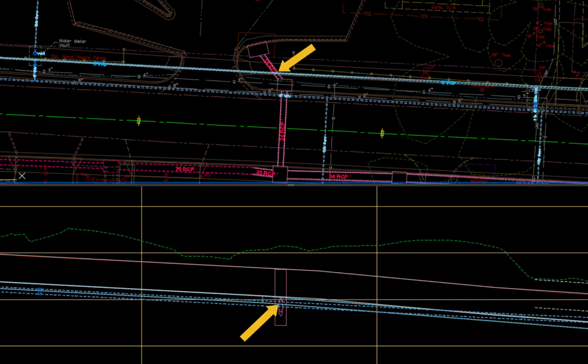There is a conflict with the storm pipe crossing around station 15+60 in Kincaid. The water pipe could be deflected below the storm pipe. The storm pipe could be lowered, which would possibly require the lowering of the sewer pipe. The normal 30-inch minimum depth of cover for a water line is not an absolute. At times, in order to clear obstructions, the depth of cover may be less than 30 inches.